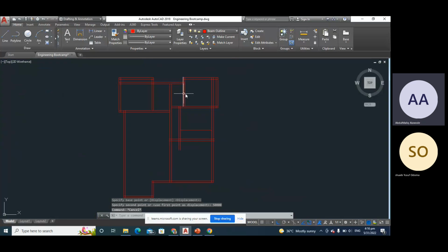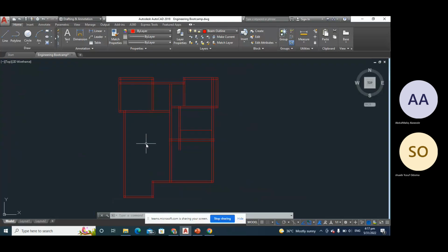So last week we were able to do all this, and while doing this, we considered the aftermath. What I mean by aftermath is, when we are done with this floor GA, what are the later things that might come in? That was where we said we can plant our column later on, so the column can support the roof beam. Although we have not reached the preparation of the roof GA, while preparing your GA, you must consider what is coming later also.